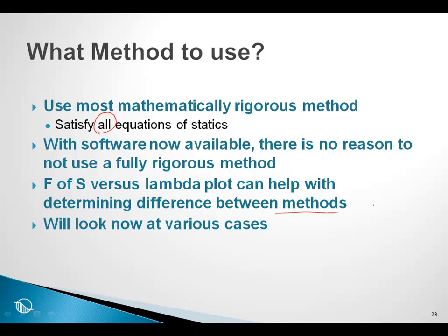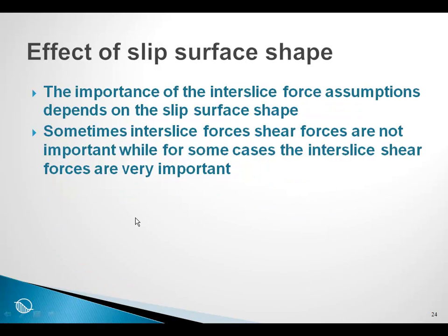We will now move on to a different subject, and that is looking at various cases and the effect of the shapes of the slip surfaces. Recall that in the limit equilibrium formulation we have to make an assumption about the interslice forces.